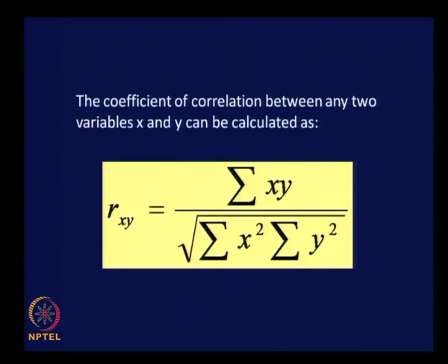And in practice we may have to deal with more than one independent variable to develop trip production models. So when the number of independent variables increases, the complexity of analysis increases exponentially, and this complexity can be tackled by resorting to the available program packages, and you can do regression analysis involving any number of independent variables and develop trip production models.